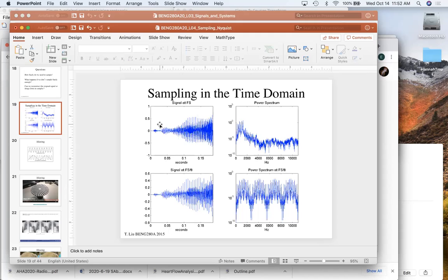Okay. And in this case, if you look at the frequency spectrum and you're seeing a signal that's like 10 kilohertz, would that mean that you want to sample at 20,000 hertz? Exactly, yeah. If there is something out here that is important to the information being carried by this signal, then you certainly want to sample at twice this frequency in order to get this replicant over here. You're still going to have a replicant, but it'll be over here, and then the signal will come down here and it'll just start overlapping here.